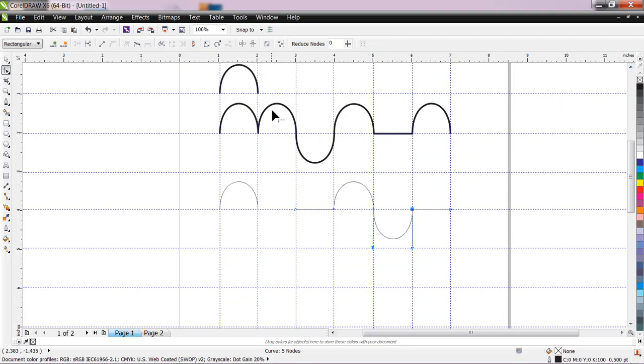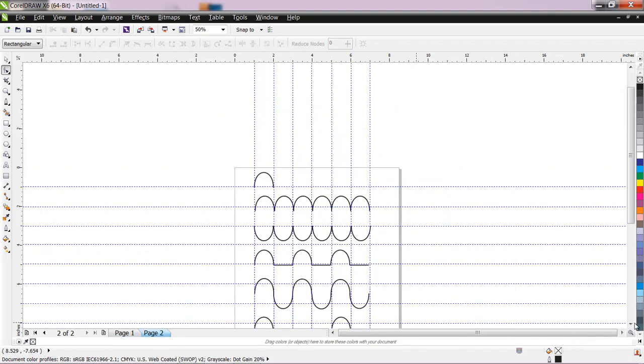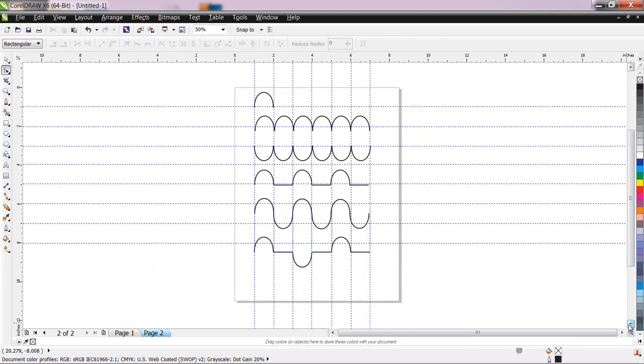Then I would like to request you to first keep practicing with the help of Bezier, and then you can use the pen tool. Okay, and you have to create patterns like these for best practice. Okay, it is very simple, but don't take this practice lightly, because whenever you want to curve anywhere, you have to use this technique. Therefore, before going to create any small object of curve, you have to first practice this, how to make a simple line into a curve.